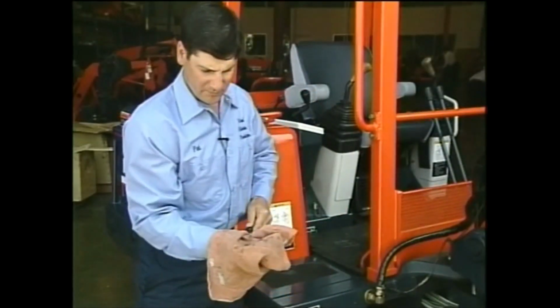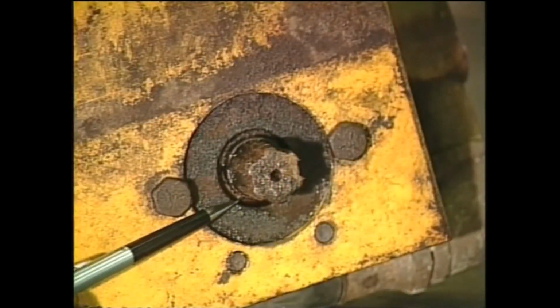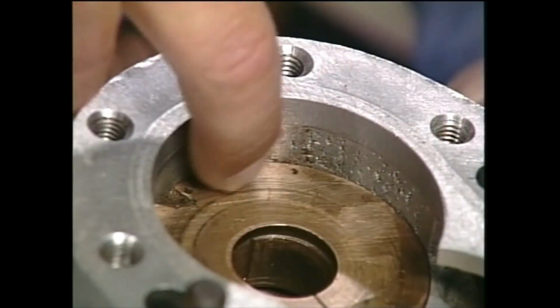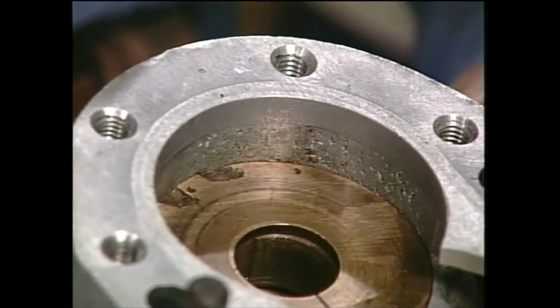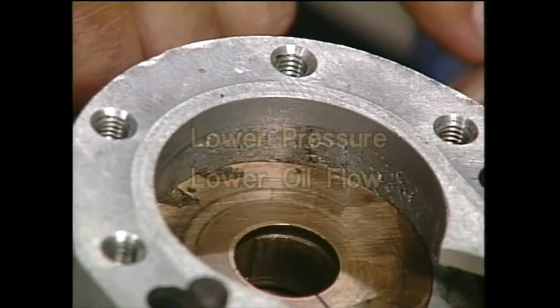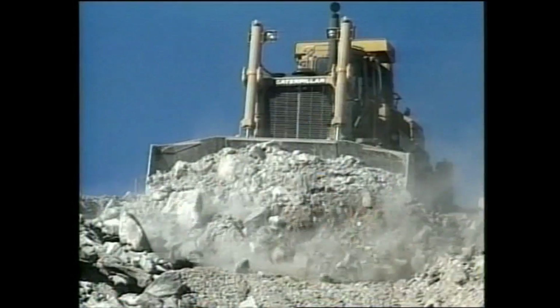Hydraulic pumps generally last a very long time if the oil is kept clean. However, dirt contamination, rust particles, and metal chips caused by cavitation and aeration can develop wear on a pump's close tolerance metallic surfaces, resulting in lower pressure and lower oil flow. The hydraulic pump drive shaft can progressively fracture over time if the pressure relief valve is set too high, or the shaft and pump body can break instantly if the output oil is blocked and there is no pressure relief.